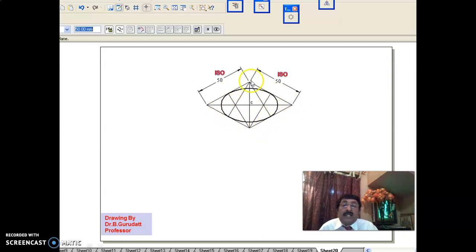These are all isometric edges, this and this, like the base of a square prism. As you know, it is all edges of the base of the square prism. The principal solid has all isometric edges, hence these should be reduced. You drew 50 iso, that is, select the entire thing and multiply by 0.816 so that it becomes 50 iso.